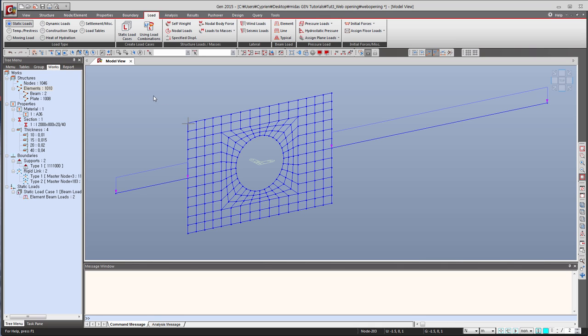Now you can use the zoom if you want, but I think for me it's okay like that. So what I'll use is, you have an option called select by polygon, yeah, this one, and now I have to select the nodes from these faces, but be careful, you shouldn't select the two end nodes, only the nodes from the middle.